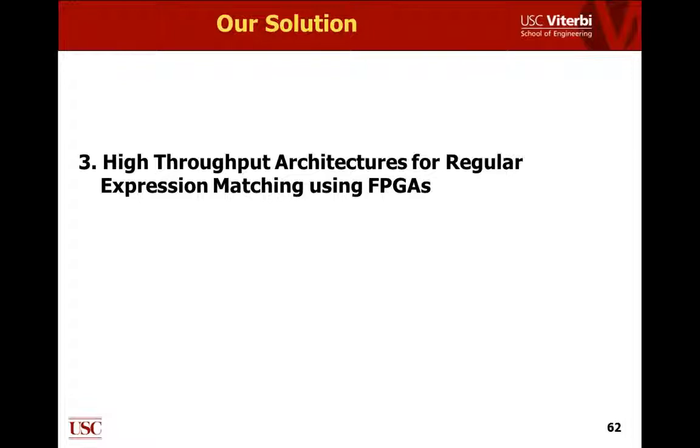And then a large number of such expressions are given to us, and we want to be able to look at the entire payload and then see if there are any matches occurring, and then take corresponding actions based on the particular match that occurs in the incoming traffic. So now when we do this, throughput is important. The number of regular expressions used in those implementations is important, and we also want to ensure that we can implement them by exploiting some of the features of the FPGA devices, so that very high performance can be obtained by exploiting the individual connections you have on those FPGA devices.